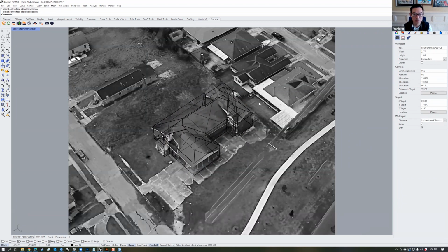First, once you get your building lined up, you want to lock in the properties panel on the side, choose this lock checkbox on the side under projection. That makes it so that when you try to rotate, it doesn't move anything in the view. So now it's kind of like locked.